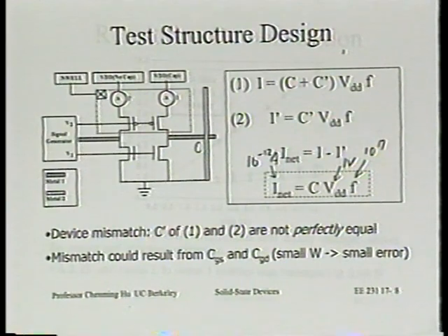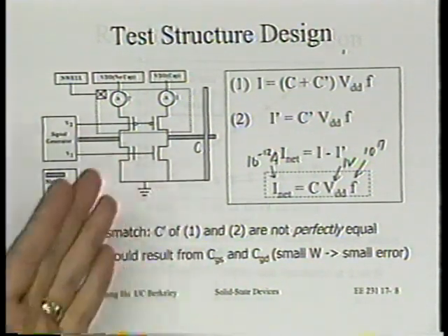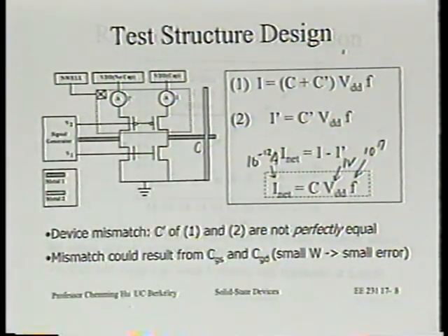So then go back to the physics here. 1 electron, does that really work? Does that not really work? Very interesting question. And I think at some point it will become probabilistic. I think you were forced a little bit to think about this when we talk about telegraphic noise, right? You have this only 1 trap, depending on the trap energy relative to the Fermi level. It says it should be 0.7 electron should be there. How is that possible? It probably means 0.7 of the time an electron is there, 0.3 of the time an electron is not there.